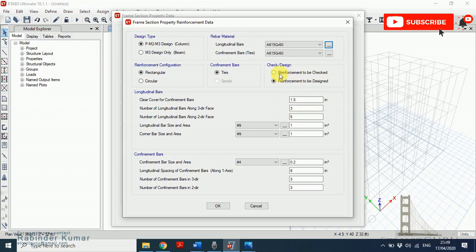And this option, reinforcement to be checked and reinforcement to be designed. Always go for reinforcement to be designed, because that means ETABS will tell us the total area of steel needed to resist the load which is assigned on the structure.